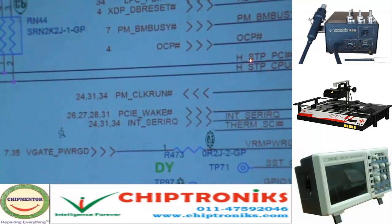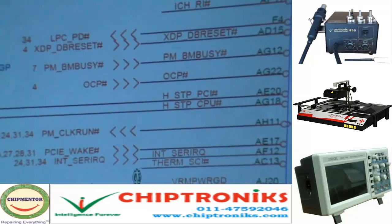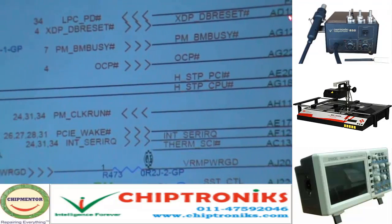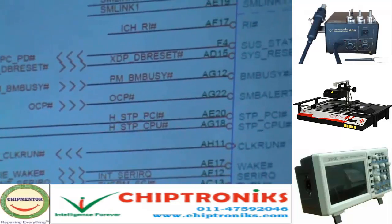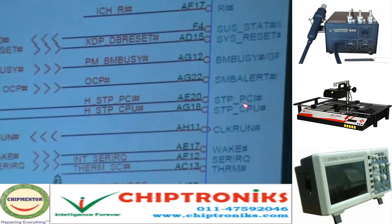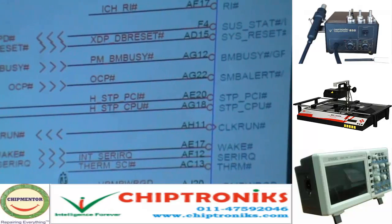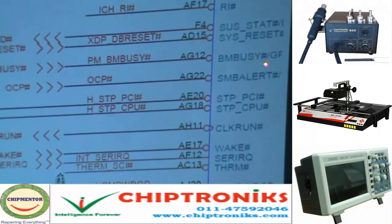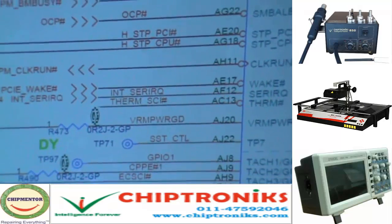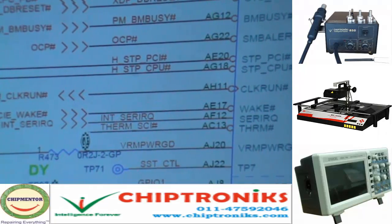VRM power good. There are many important signals there, like BMBG, that is called bus master BG. If this signal gets reset, then your bus master, whatever things are there in your bus, like the SM bus, will get reset. System reset is also there, but the important signal from the testing point of view is VRM power good, because you can measure only this signal over here in this section.